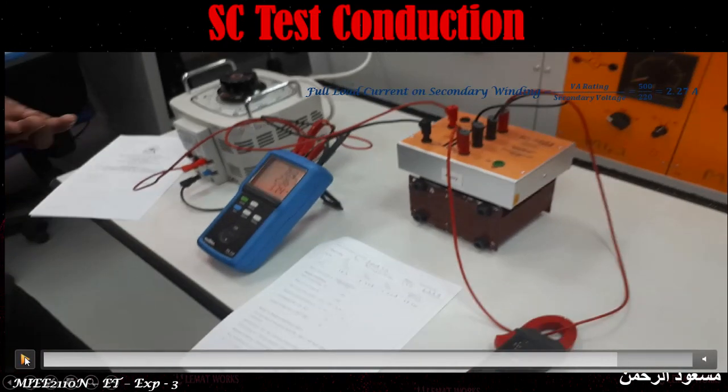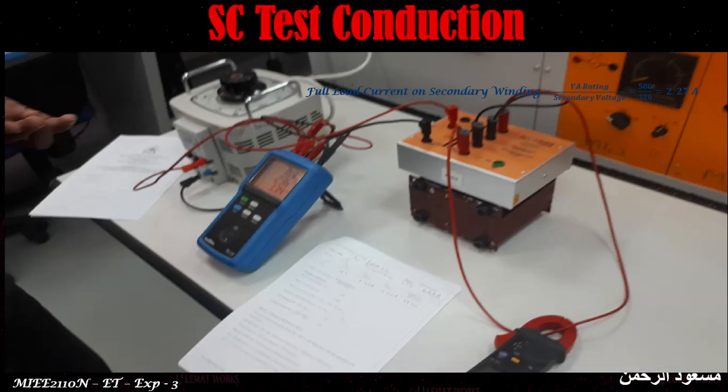As I explained in the OC test itself, the open circuit test is conducted to find the core loss in the transformer, and the SC test is conducted so that the wattmeter WSC reading will indicate the full load copper loss.